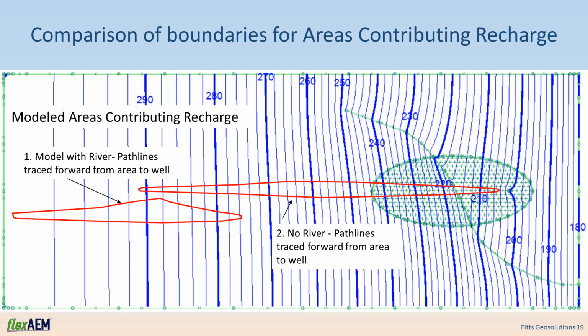One final thing I wanted to show you is a comparison between the area contributing recharge for this model and the ACR calculated for the same model with the river removed. You can see that the recharge area with no river capturing shallow groundwater flow is much narrower and covers the area directly upgradient from the well because the flow field is not distorted by the hydraulic effects of the river.